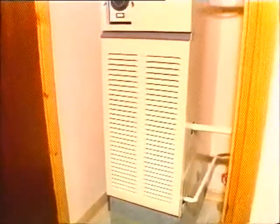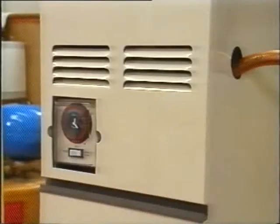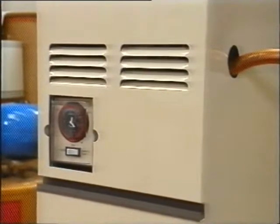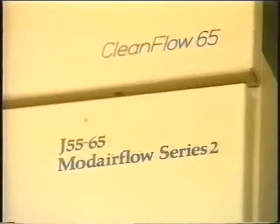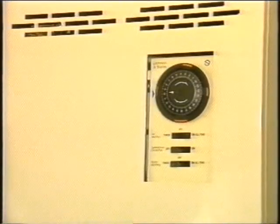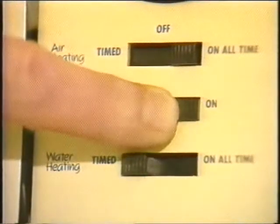There are many different types of heaters. The one you choose will depend on what output's needed, whether the flue system's room-sealed or open, and where it's going to be installed, in a room or a compartment. Models can either have traditional controls or what's known as mod airflow. Mod airflow uses electronics to improve comfort, performance and economy.